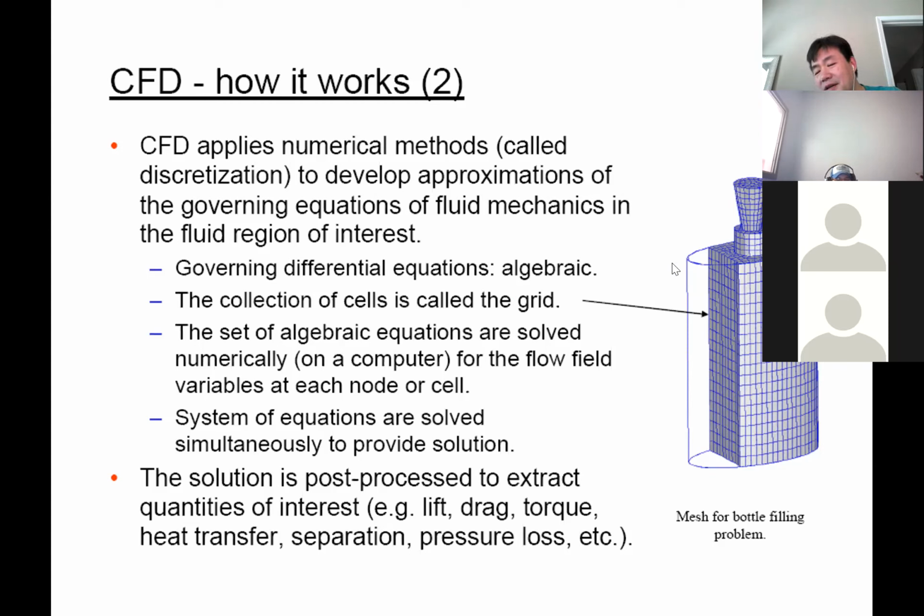This is the confusing part in real-world problems. A lot of people say, hey, I'm simulating a flow over a house, for example. They try to make the house in AutoCAD or in Workbench of the software, and they made a house, then they place the mesh inside the house. That's wrong. It's opposite to this problem.